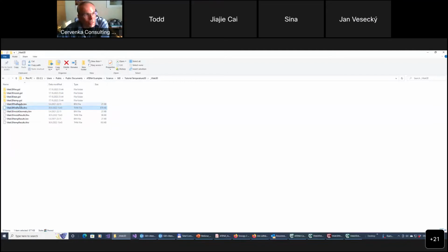Here I want to mention this bin file, which contains the geometry. This is actually a very useful, very important file. And I want to emphasize that because this allows us to use different models, different geometries, different meshing for the thermal analysis and for the stress analysis. And the program will then interpolate the results to the new mesh.